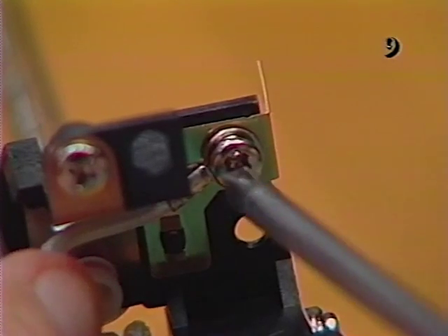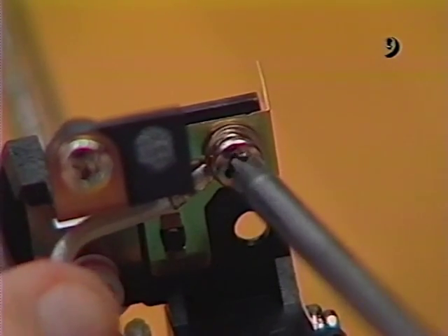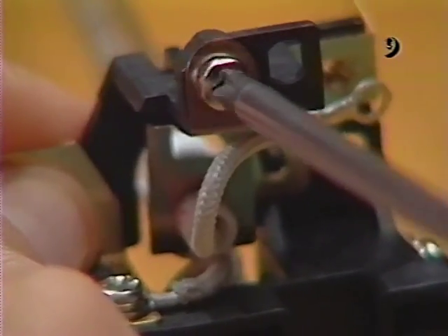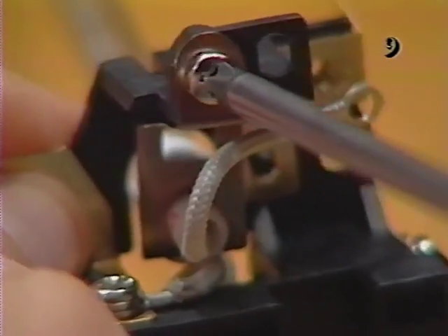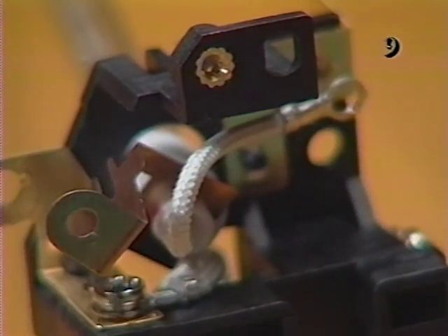Remove the silver screw and washer that secures the heater bulb to the left connector holder. Now remove the small silver screw that secures the gold-colored spring leaf to the left connector holder. The spring leaf holds the heater bulb in the correct position.